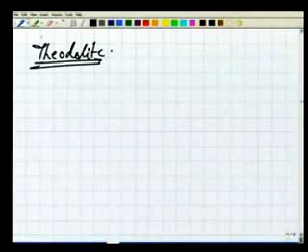Now, till I reach total station, I will keep saying theodolite, because total station and theodolite, basically the principles are same. Total station is an advanced version of theodolite, which also has some distance measurement within it, and also has some extra software in order to do some computations. So we will go to total station later on, but henceforth we will only talk about the theodolite.